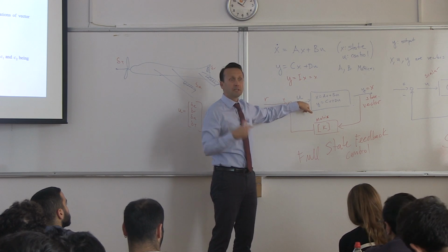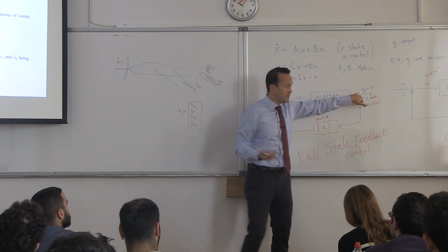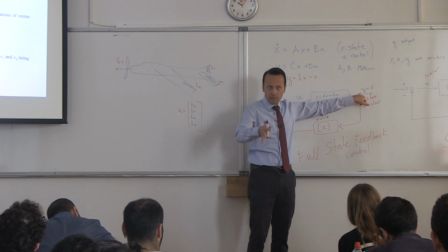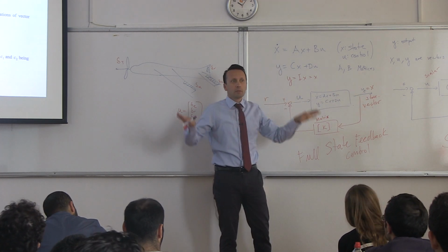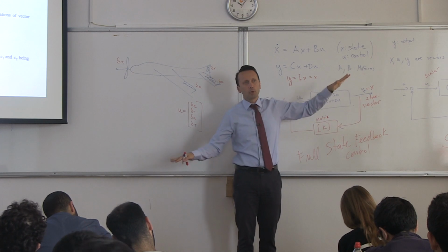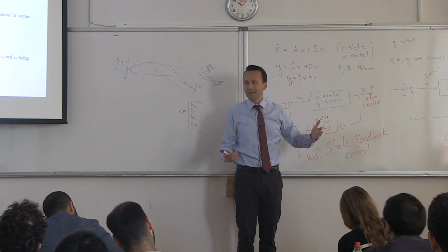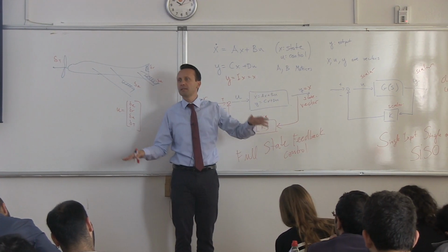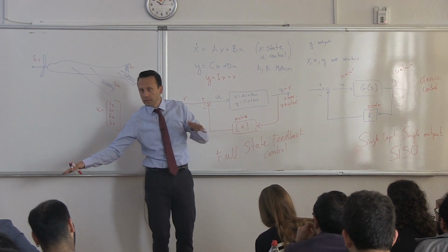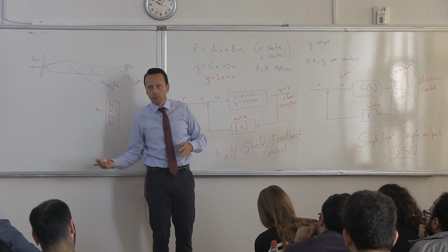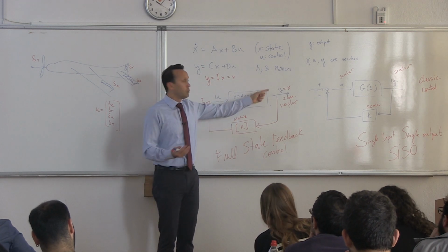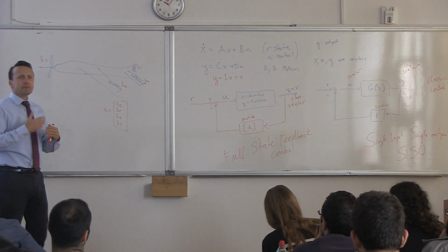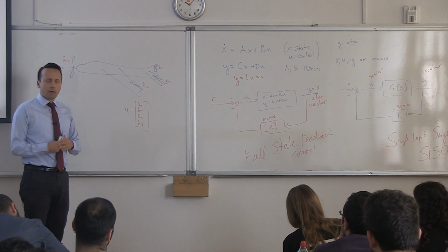So what will be the response? What will it do? Well, that's the output. That is what comes out. You give an aileron input, the aircraft will start rolling. So you will have a roll rate P, and then you will produce a phi, and maybe because of the dynamics, you might even get some pitch, or you might just be falling down. You might get a side slip, a side velocity, and things like that. That would be the output. What happens in time after that input is all your output.